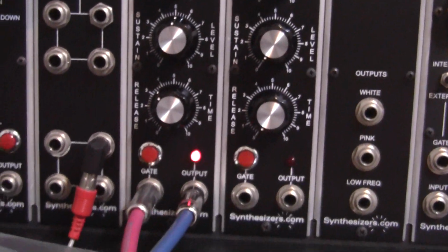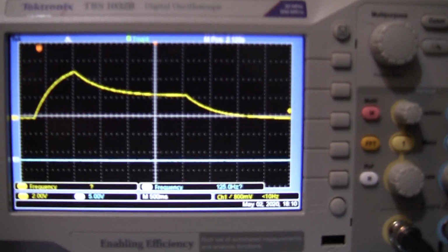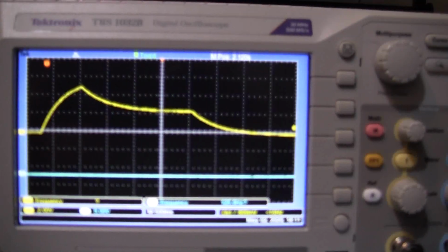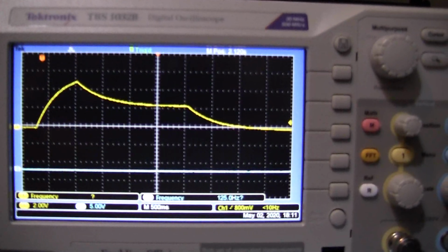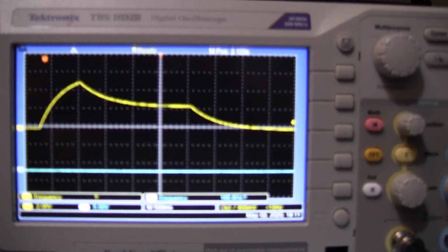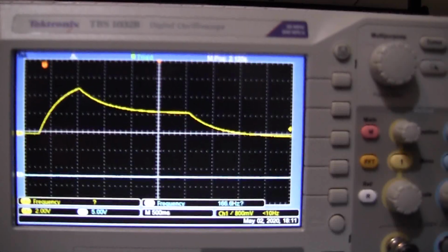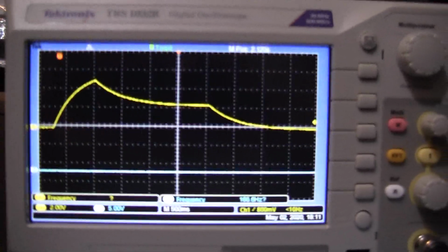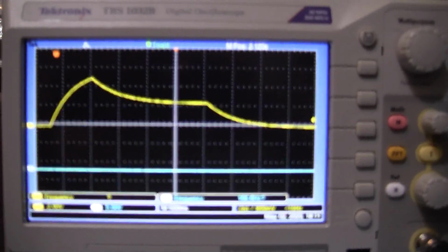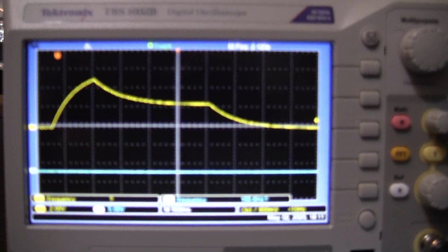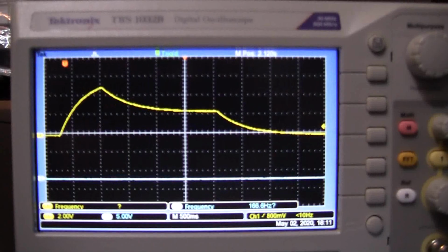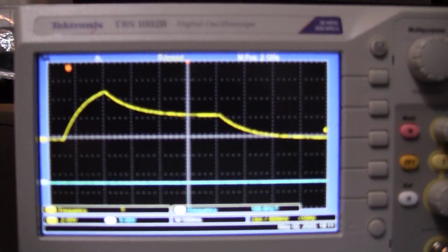on the oscilloscope. Now this is really an example where the digital oscilloscope shines through, because for these kind of slow times you wouldn't be able to get such a nice steady waveform on the analog oscilloscope because of the necessity of having the phosphor tracing. But because this LCD is drawn from memory, we have a much better chance of seeing a perfect waveform on